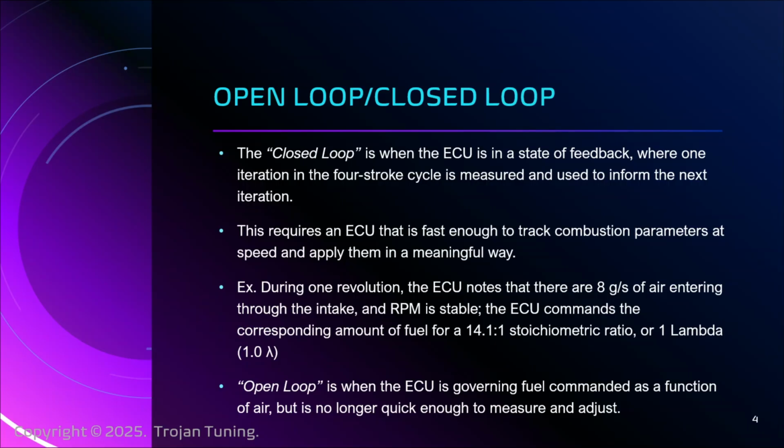is much quicker. And not only is the ECU a limiting factor, but the sensors themselves in the engine are a factor. And they can only move so quickly to produce meaningful signals that go to the ECU, which you can then mitigate. So 99% of tuning, I would say, over the past 20 years or so, since we've had OBD2 and direct injection in particular, the tuners have had to manage closed loop and open loop very carefully. And we're going to talk more about all that in a sec.